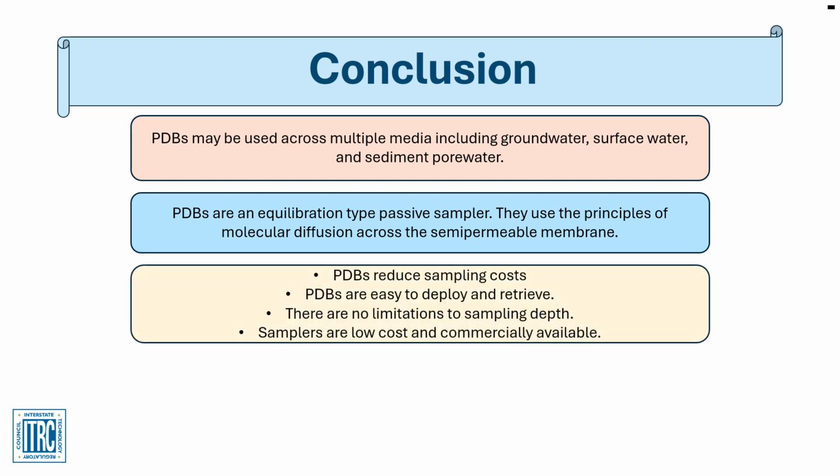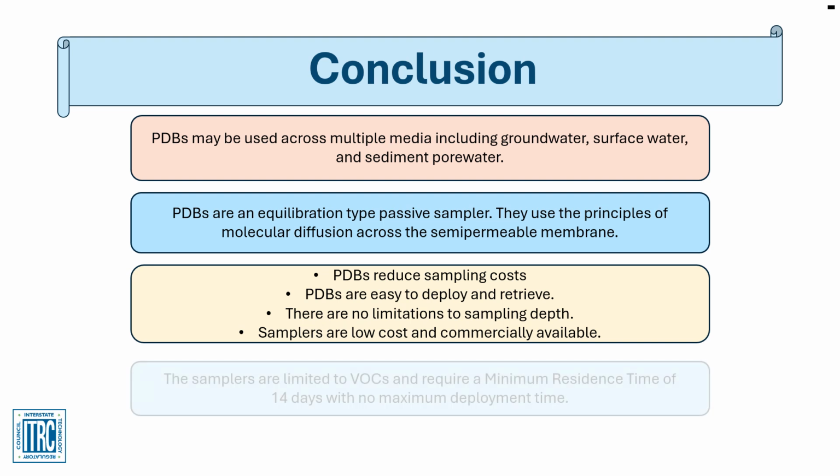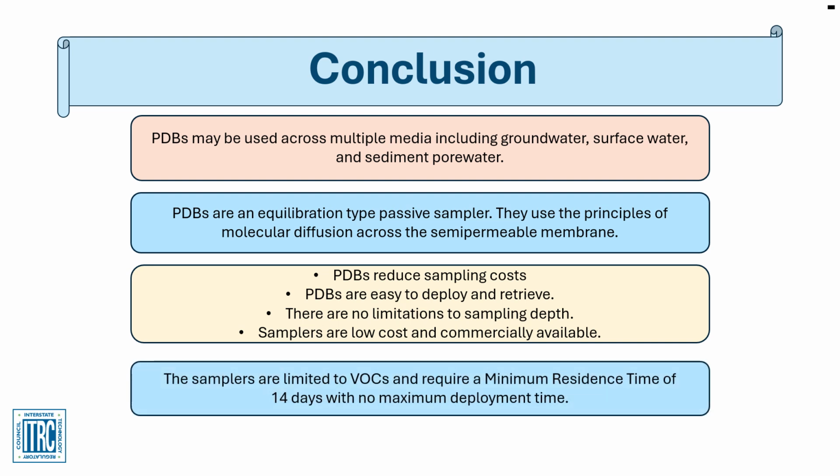PDBs are easy to deploy and retrieve. There are no limitations to sampling depth. Samplers are low cost and commercially available. The samplers are limited to VOCs and require a minimum residence time of 14 days with no maximum deployment time.